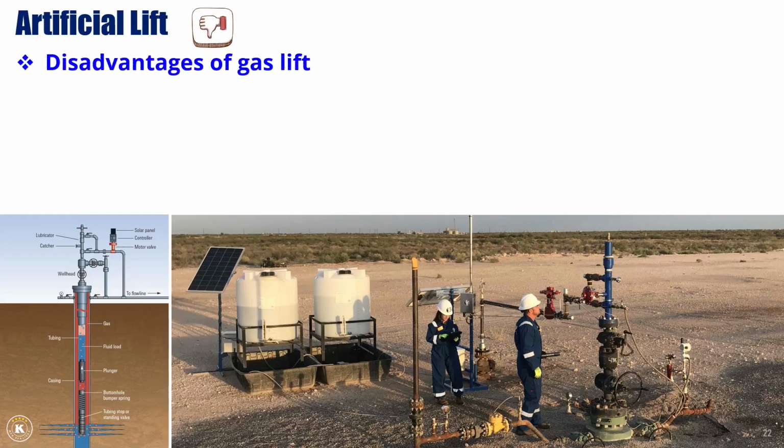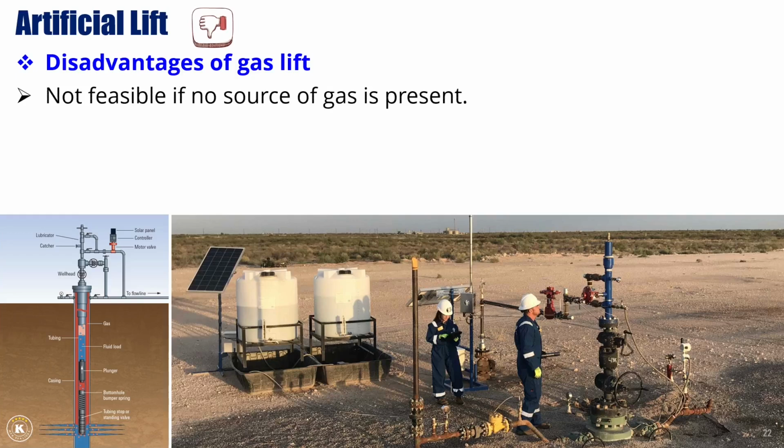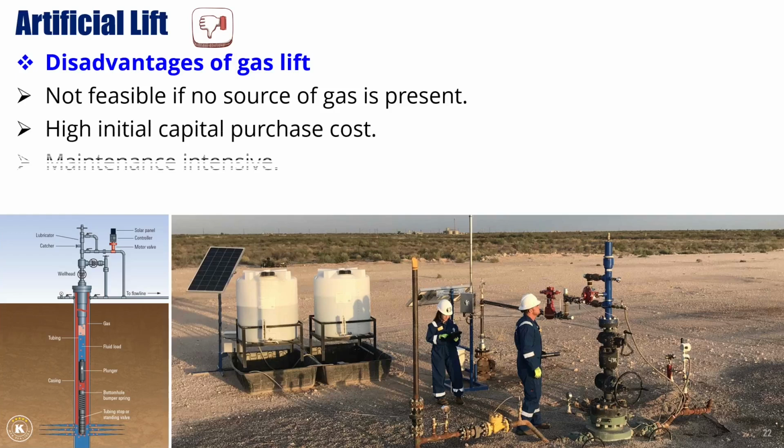Now, let's look at the disadvantages of gas lift. First, it's not feasible if there's no source of gas available. Second, the initial setup comes with a high capital cost. Third, it requires intensive maintenance. And finally, operating it can be quite challenging.